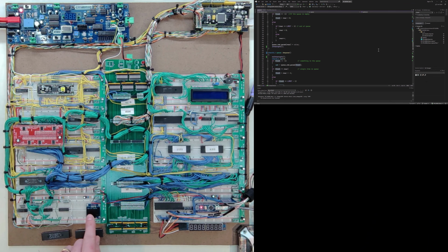Also, my OLED screen, I was powering off of the main system power. I've moved the VCC for the OLED over to the Nano. So basically, when I apply USB to the Nano, that OLED can be initialized and be ready to go. And that way, when I turn on the system, I don't have to initialize that screen. I don't have to worry about waiting for the initialization. It's ready to go. And I'm finding that that is working much better.